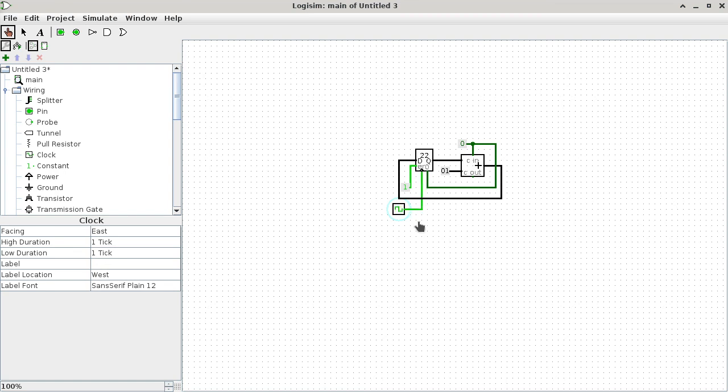So think about, what if I connect the output of the register to the A port of the ROM? Then I would just be going like, okay, go to location 0, now go to location 1, now go to location 2, now go to location 3. So I have the most basic mechanism of quote unquote automating something. Because now I can specify instructions, so to speak, in the ROM and just say, do this first, and then do this, and then do this, and so on. So I have the very basic mechanism of quote unquote automation.